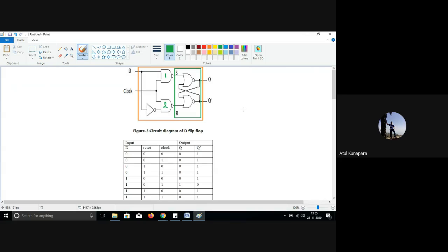we were giving either a set condition or a reset condition at the output side, right? When R equal to 0 and S equal to 1, it gives you output set. That's the condition for this SR flip-flop. Let me draw that table just beside here so you can get the idea.